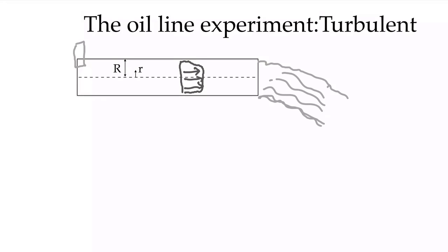The very interesting thing is, recall that I said that a turbulent flow has a higher pressure drop. Well, what's happening in this system? In this system, we're setting the speed on a pump to drive a flow rate of oil through this system. If the flow is laminar, the pressure drop is lower than it would be if it's turbulent. So let's say we manage to keep a laminar flow up to a Reynolds number of 3,000. We get a flow rate that corresponds to that solution that we've shown for that pressure difference across that pipe, and it's the laminar solution. We have a given pressure drop.